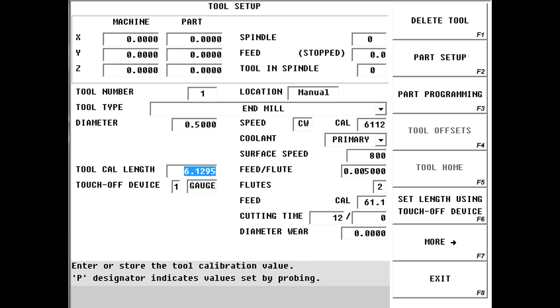And the second thing I want to do after I've made sure that the tool is created and described correctly is go through and associate some speeds and feeds. The reason I do that is as I pull this tool into a program, if the speeds and feeds have been created already, it will populate the speeds and feeds fields in my program.